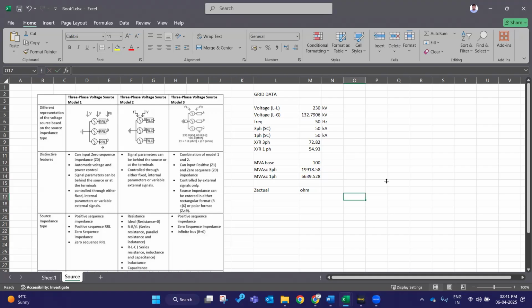No, no, both are in kilo only. See, here it is not volt, here it is not ampere. Yes, of course, Saravanan, that's what I'm saying. This is MVA only. Not entering the unit made you confused, right? So MVA only. This is a basic thing only. Here all the units are in kilovolt and kiloampere only, so directly the value you are getting is actually MVA. Clear.